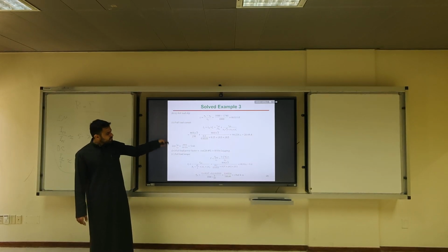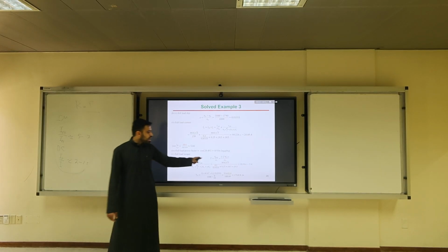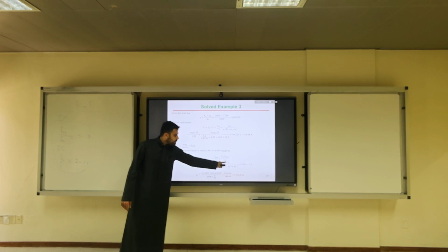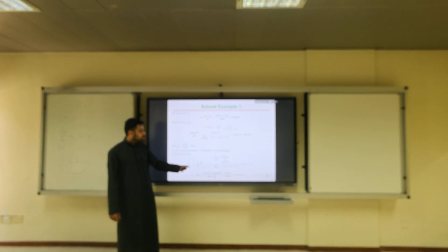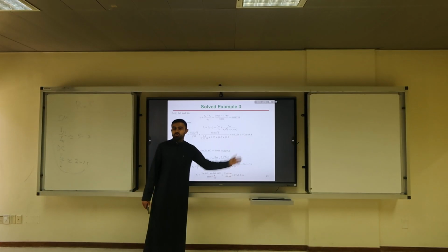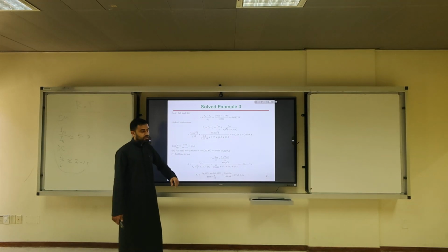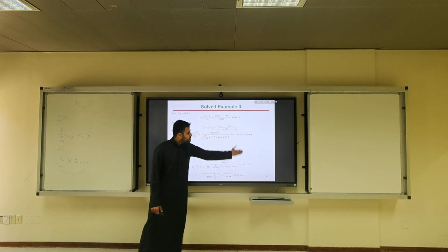The other question, which is very important, is to find the full load torque. The full load torque is again the air gap power at a different slip over synchronous speed, but you still need to calculate I2 at full load. What is I2? It is this term. If you don't have time in the test, just put 44 and move on. Who cares about 3 amps? You can approximate anything. You can ignore the parallel branch if you don't have time. Maybe you'll get 8 out of 10, but it's better than 0. So you can approximate 41, whatever.